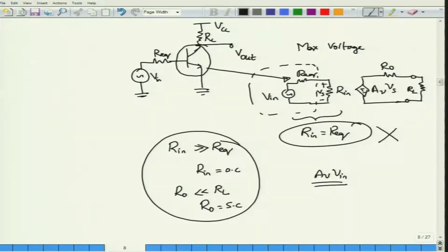So, what is going on? I mean, why is it that low frequency people do not talk of impedance matching, whereas high frequency and RF circuit designers are always talking of impedance matching? Okay. The reason is, in the low frequency case, this lead, to which you are going to connect a load resistance RL, can be considered to be a wire.